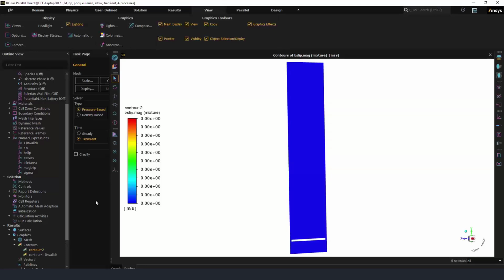If you're a user who only wants to do basic CFD, then Fluent has a really nice Pro option, which has limited physics, but still contains the meshing, can go through and do flow, heat transfer, species, and has all the full expression language. And I think that is really key now. There's lots of things that you can do in expressions that directly allow you to set up problems. And what I'm seeing more and more is that you can use expressions to eliminate spreadsheets, so that when you've got to do some basic conversions from volume fluxes to velocities and that, do it all as expressions, and then it's all documented for you. The other thing, of course, is that these get evaluated and put out in the report.